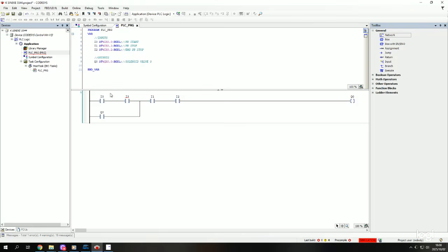So these two components are for advancing our piston rod. These use either of the two to retract. So our code, we are done with our ladder logic. We've added our code. We need to add I3. A sensor is an input, so hence we are adding it this side. Change this to 3, and then you can either say sensor 0 or proximity sensor or S0, whatever name makes sense to you.